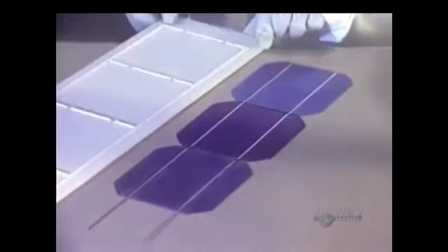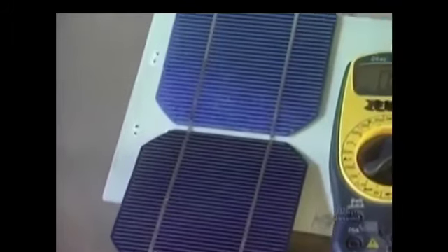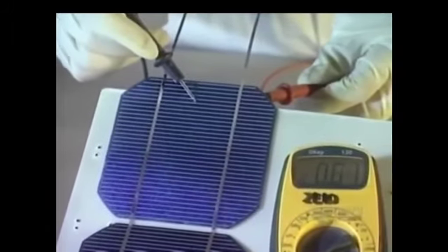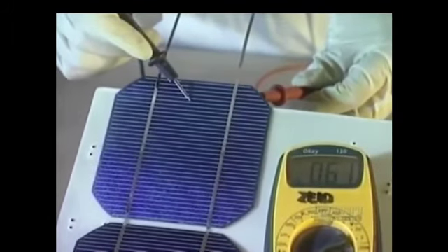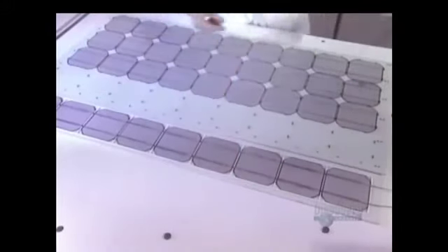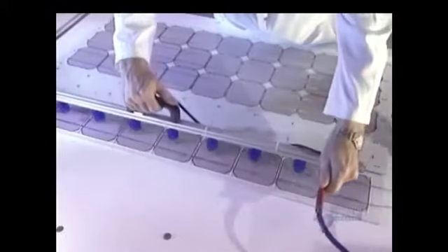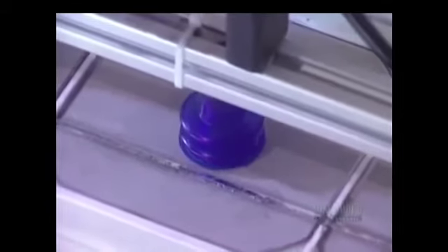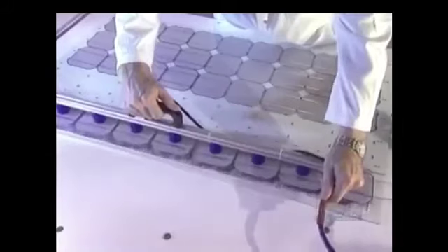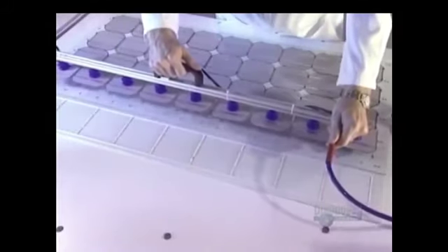Modules are assembled end to end. They have to be handled with great care. Using a voltmeter, the voltage of each module is verified. At this stage, it's easy to remake a solder connection if there's a problem. If the voltage is adequate, they use suction grips to make handling of the 9 rows of modules easier and to keep them clean.